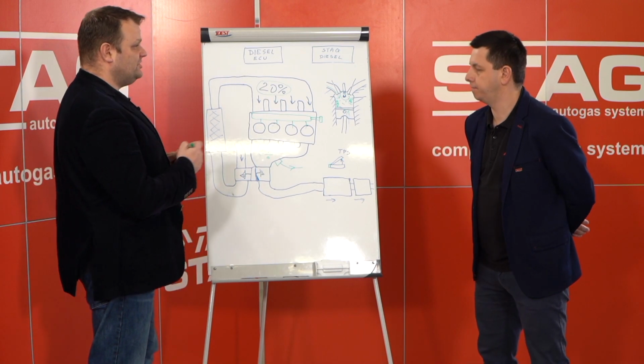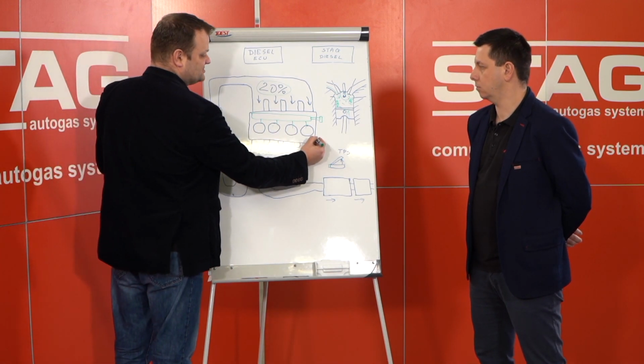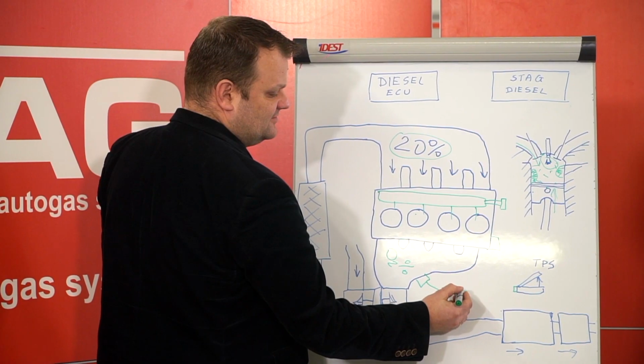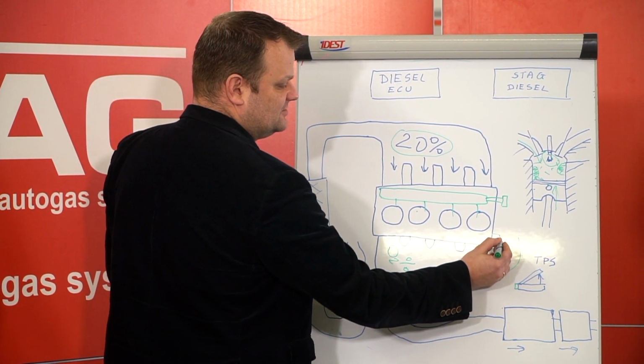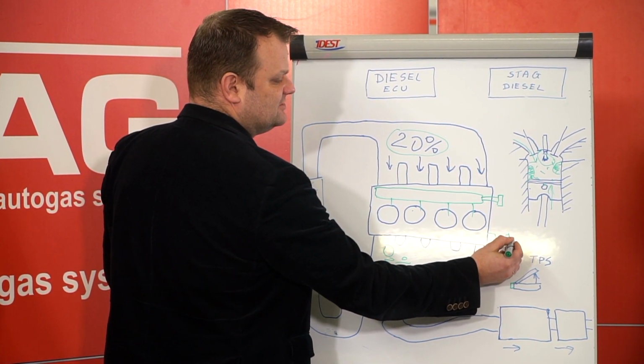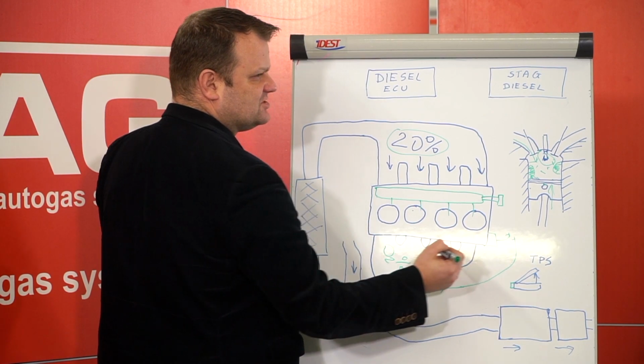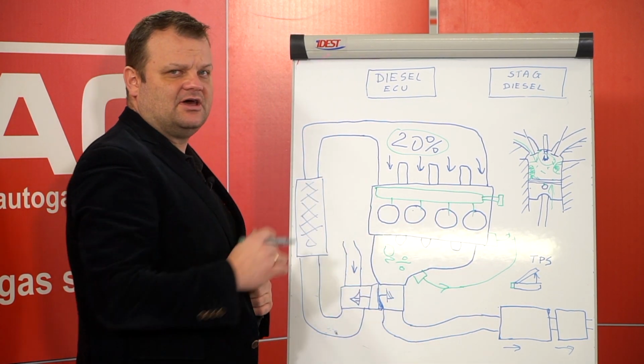That's why we need to add an additional sensor, a knock sensor. So we have one signal, and then we'll have another, a second signal from the knock sensor, and the knock sensor should be installed on the engine block.